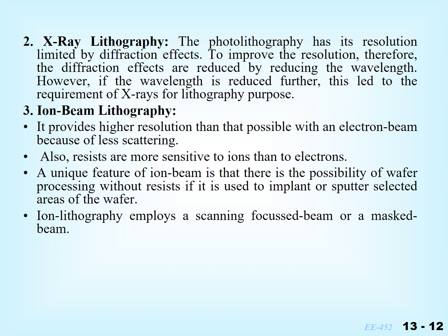Another method is ion beam lithography, which again provides better resolution as compared to electron beam lithography. Here the resists are sensitive to ions, and it requires a scanning focused beam or a masked beam through which it can be projected over the integrated circuit surfaces.